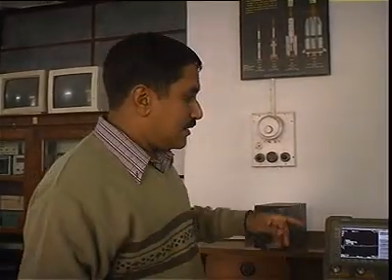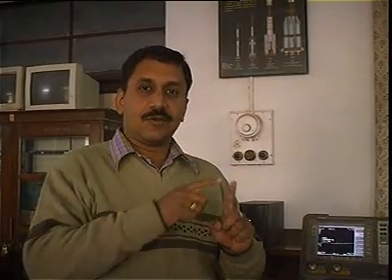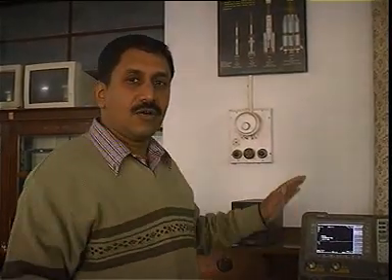Okay. Now, just like you had an oscilloscope where you had a vertical axis as the voltage axis and horizontal axis as the time axis, on a spectrum analyzer, the vertical axis is the power axis, the horizontal axis is the frequency axis. Now let's go back to the classroom and we understand what we mean by this. Suppose I have a signal which is represented in time domain by small x in brackets t. Okay, that is x as a function of time.